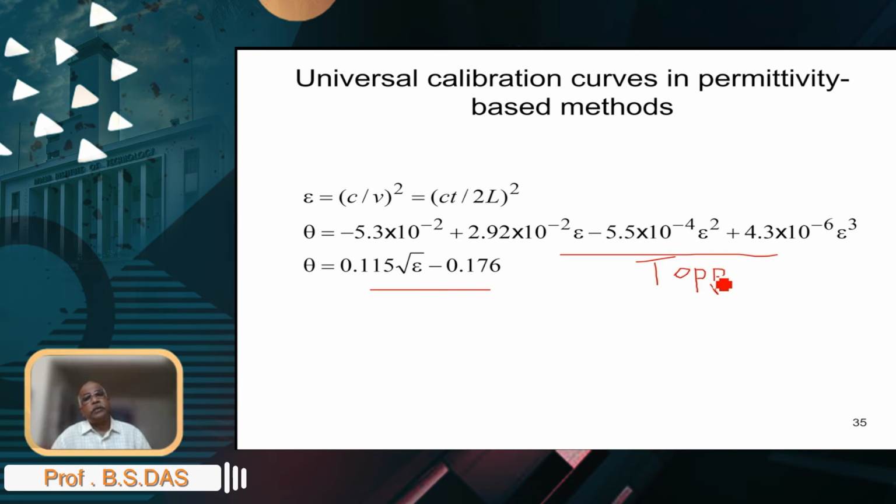Typically, in the design of these kinds of sensors, you have some kind of a waveguide through which an electromagnetic pulse is passed, and the extent of this dielectric relaxation is measured in terms of the velocity of the pulse passing through the waveguide, and the dielectric constant is derived using thin disk kind of approximations.